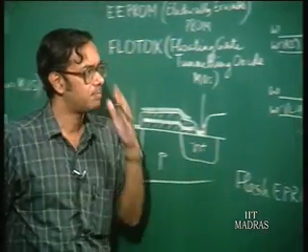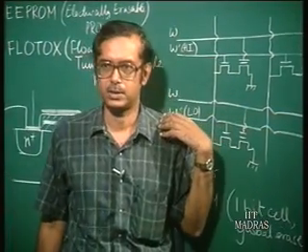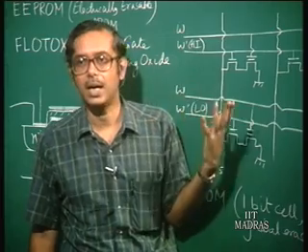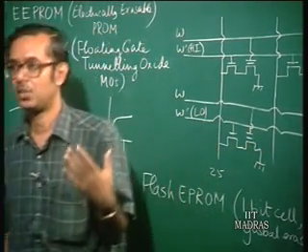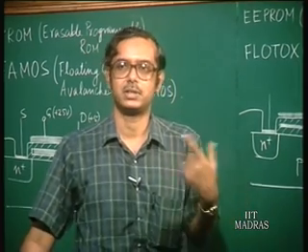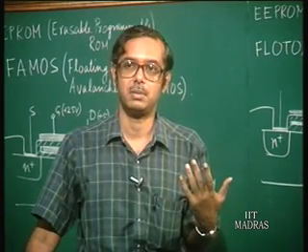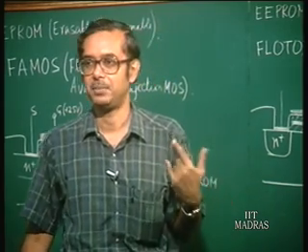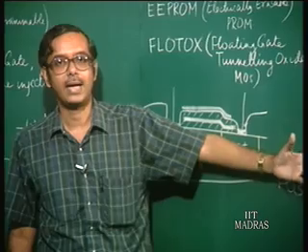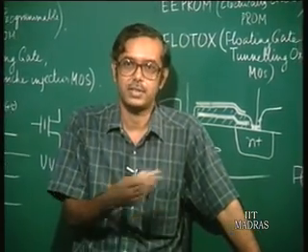So basically an ideal memory would be one which has all these good properties. Now of course none of the memories have all these properties. So there is a lot of work going on to realize the ideal memory. That is, for example, maybe a static RAM which has a single transistor cell and is non-volatile. Well, it would be an ideal memory. Or for example, a flash EEPROM which is bit erasable, and where the writing time is as small as the reading time.